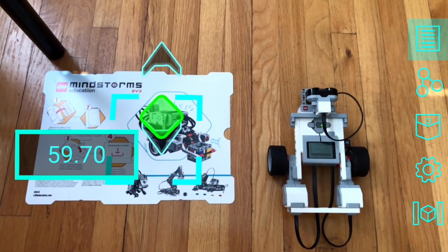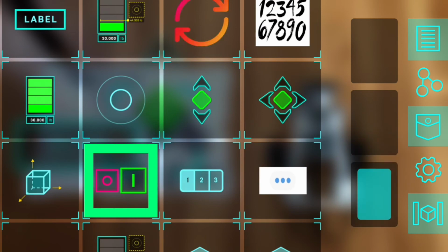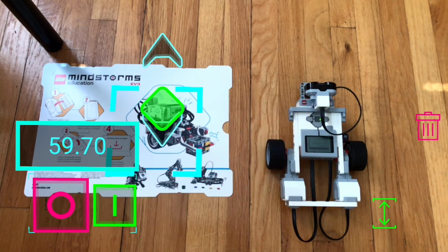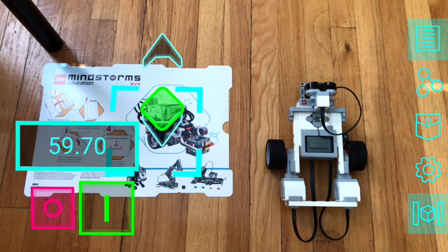So next we're going to take advantage of the motors node. So if we freeze the screen and go back into the pocket, first we're going to grab a switch. So we can drag this switch into our space, move it over to the left a little bit, and we're going to connect this up to the stop motors node. So stop motors, if this switch is on, will stop all of the motors, and so this way we can stop the EV3 from running away from us.